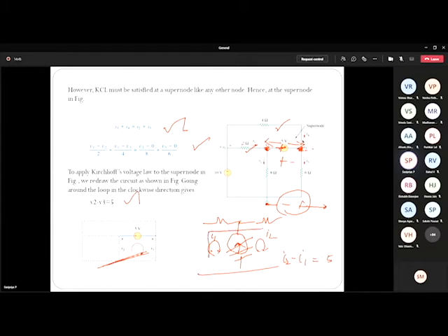And then what do we do? We combine these two loops. Same procedure here. So I replace this voltage source with the equation V2 minus V3 is equal to 5. Now I am combining these two nodes, so V2 and V3 become the same node, but the nodal voltages are different. Just remove this and consider the currents present in this node as well as this node.